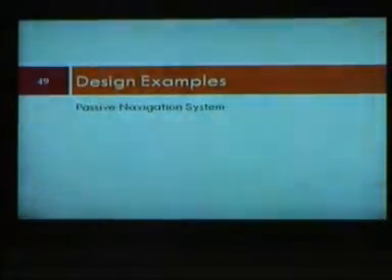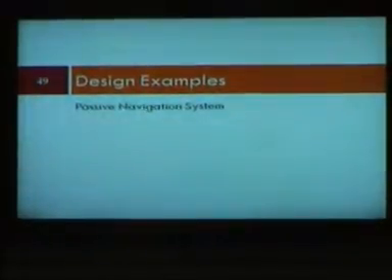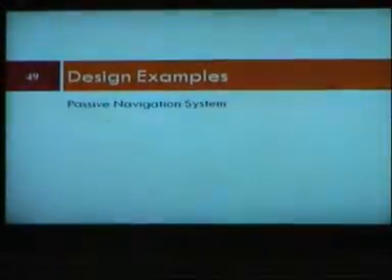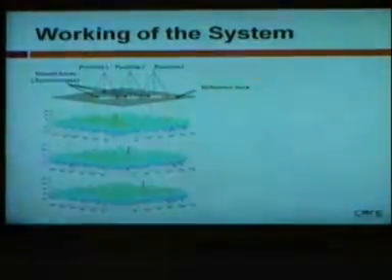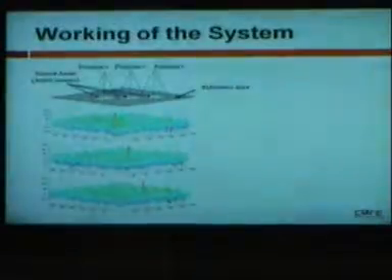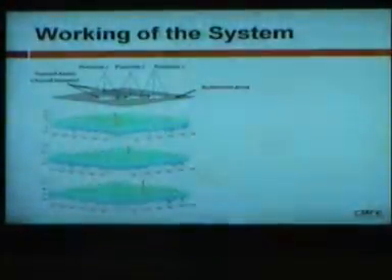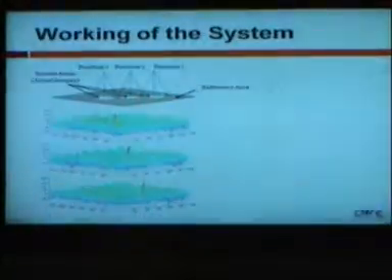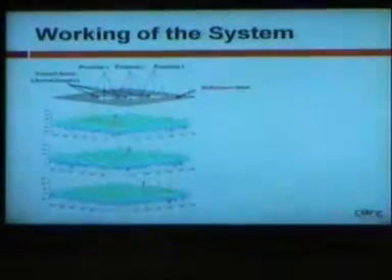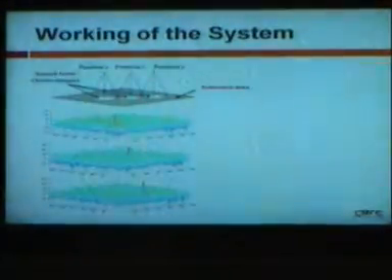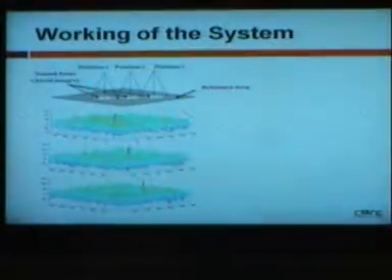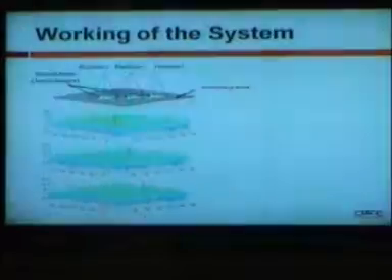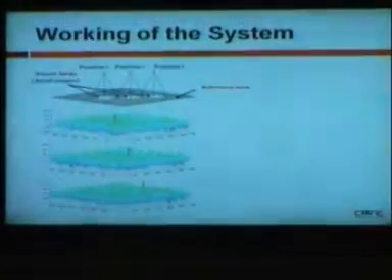This is yet another project which we did earlier, and it was a very interesting system. It was a passive navigation system. We put it on a flying object, and the flying object is looking down. It has a video camera in it, so it is taking a real video, and the platform also stores all the satellite imagery of the area. So in real time the system can locate itself, without any GPS. With image processing techniques, the bird is flying, it's looking down, and it knows where it is.